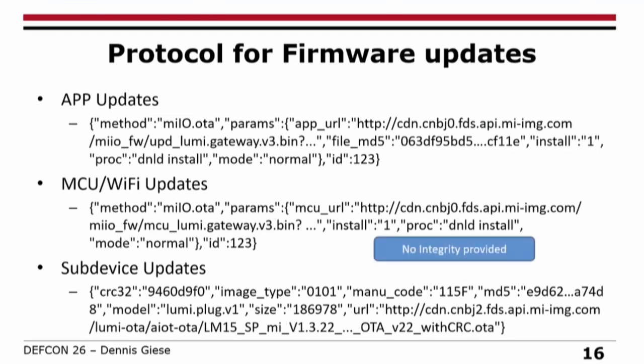The interesting thing here is the MCU and firmware updates are not protected at all. So they don't put an MD5 checksum in there, so if something happens on the download way of the firmware update, you have no possibility to actually check the integrity of it.